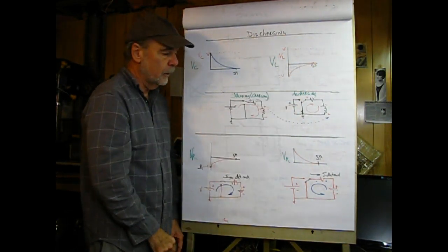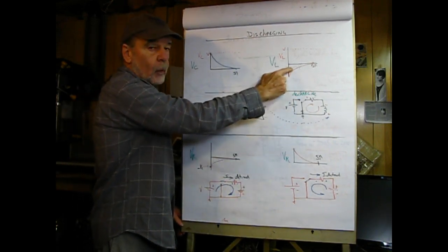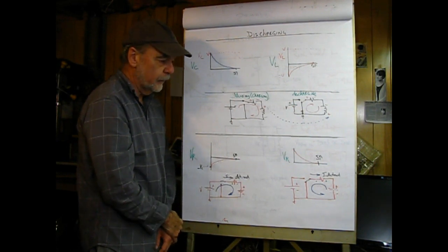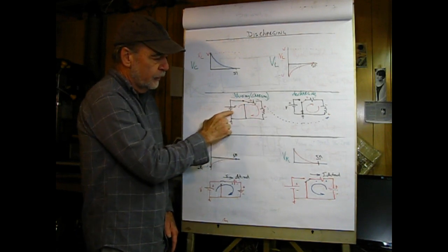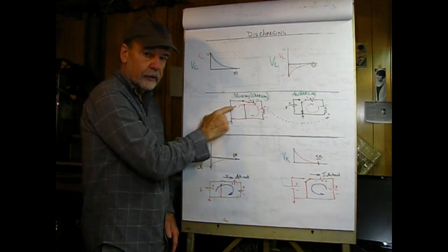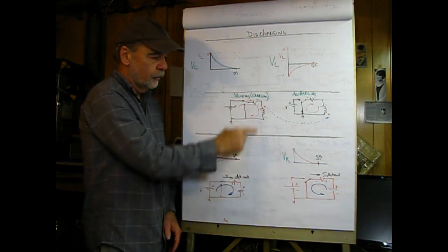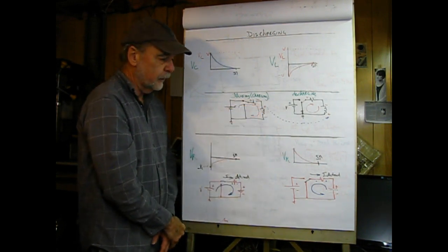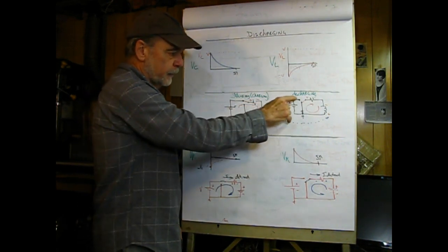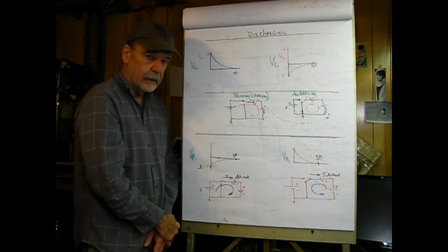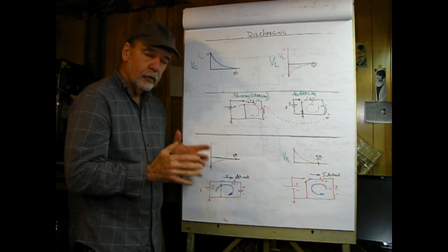Now what's that about? Well, if we take an inductor here, and this is what I'm doing here, expanding on why this has a component in the 4th quadrant, is when we're fluxing it, we have the switch in the up position and current is flowing in this direction as we would expect it to. And we say we'll have a plus to minus drop across the resistor and a plus to minus drop across the inductor. And then what will happen if we flip that switch, and this is the key difference between inductors and capacitors, is an inductor is like a flywheel.